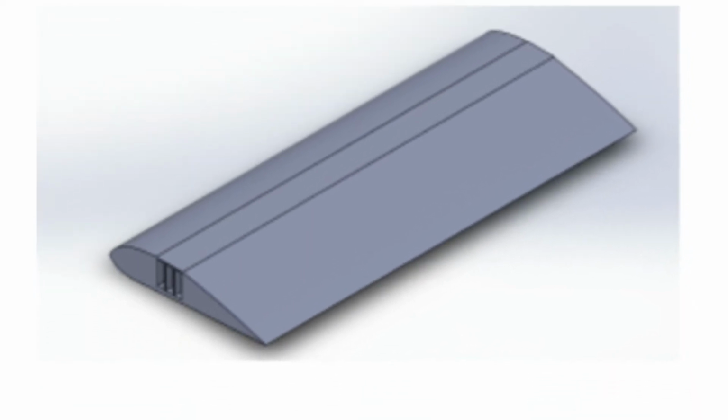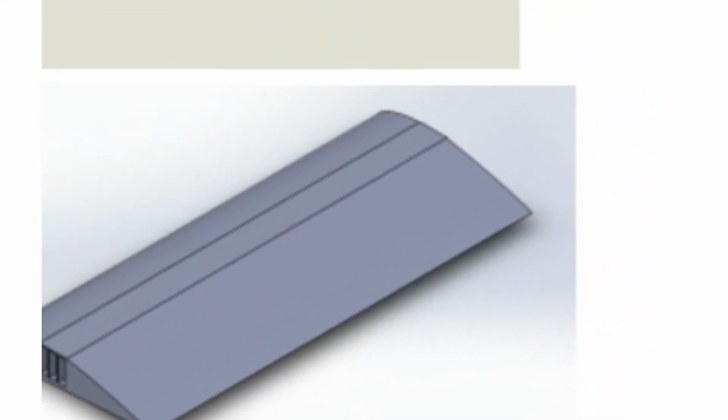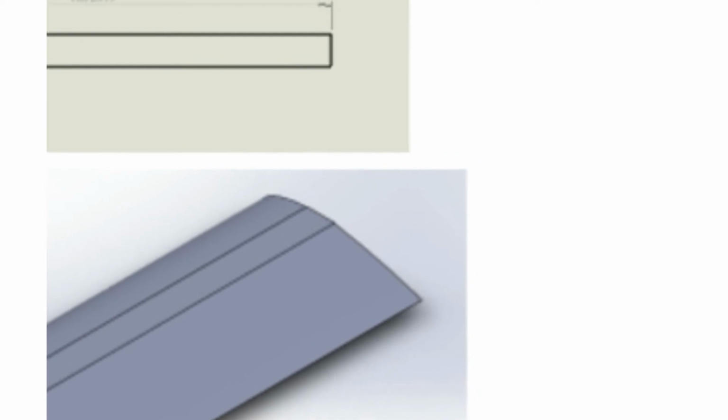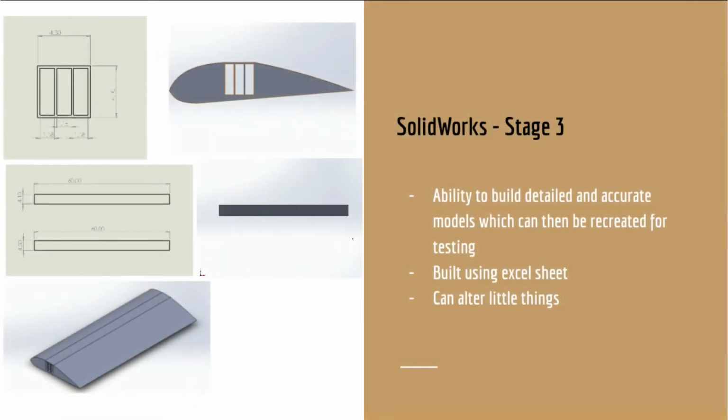The way that we constructed this beam was by using a sheet of foam, cutting it into sections, which were then rolled so that they would bend rather than being glued together, keeping it as one sheet. They were then formed into a beam with a large overlap, which allowed us to use it for adhesive purposes, which is shown in the figures below.